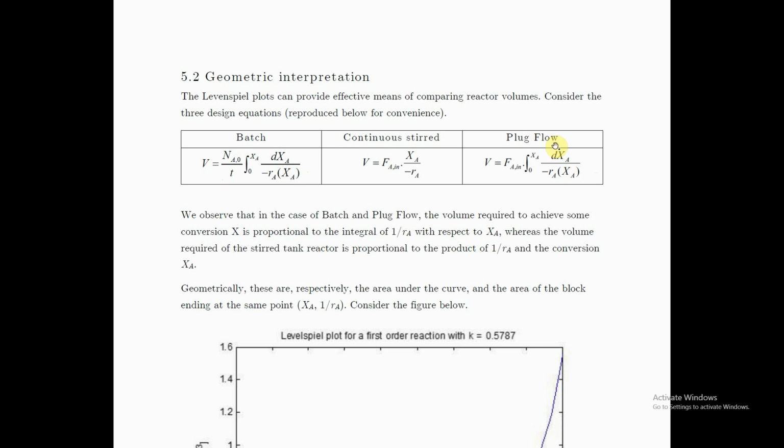A similar thing happens in the plug flow reactor. It's flowing across this tube, and near the front of that tube, you've got a high concentration of component A, and as you look further down the tube, you see lower concentrations, but at least you had a space where you had a high concentration and hence a high rate. So that's why in both these cases, we need less volume.